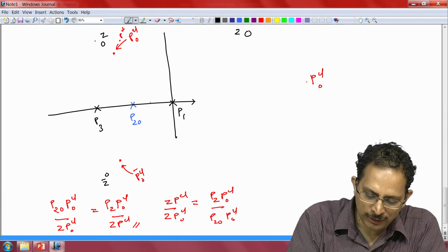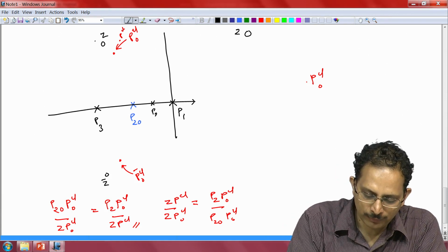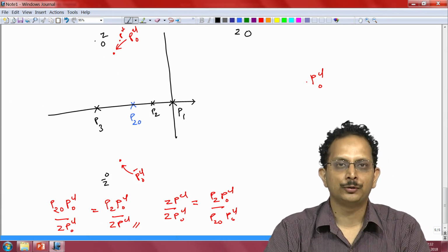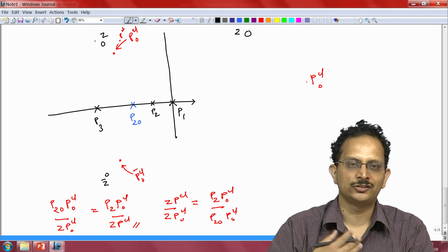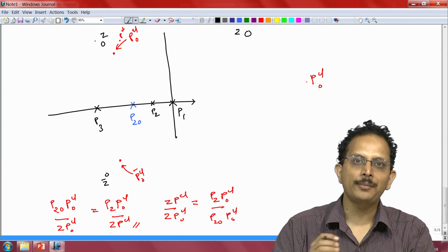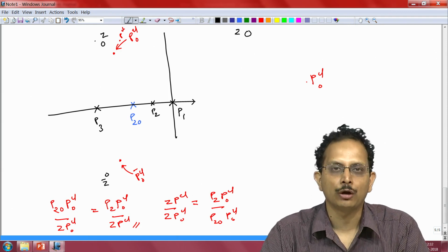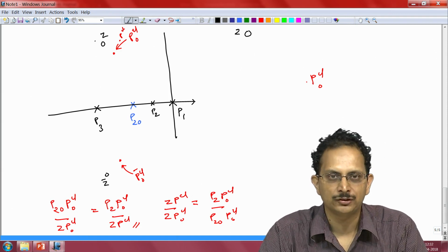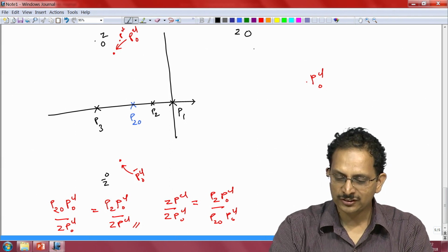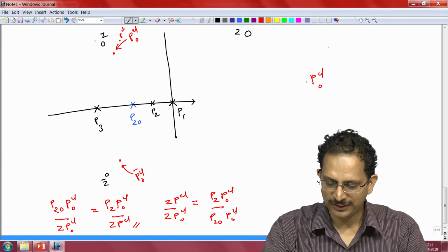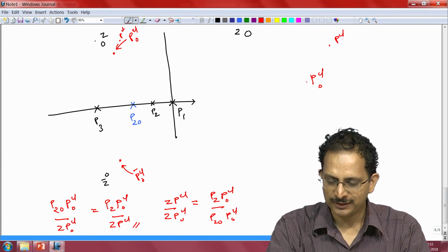plant pole is actually at the point P2, and P2 naught represents the nominal position of the plant pole, which is s equal to -1, and for this nominal position we know that the closed loop pole will be located at PCl naught, namely -1.5 plus 2j. So in this zoomed in view also I shall locate the point PCl. So it would be located, let us say, somewhere here.